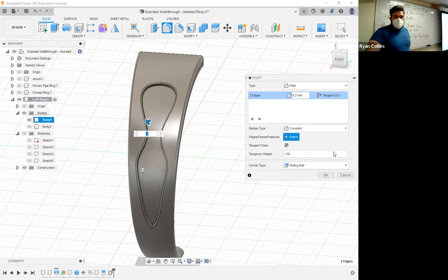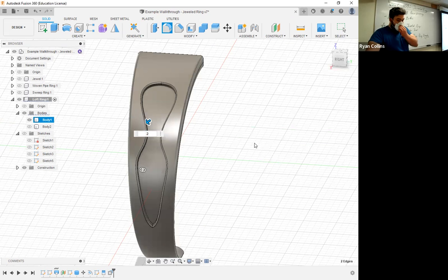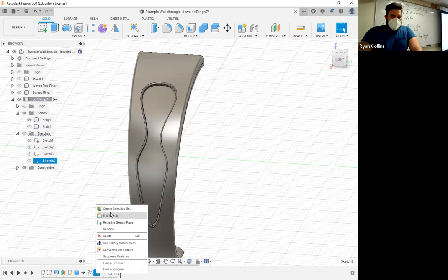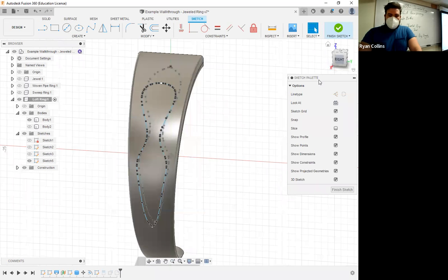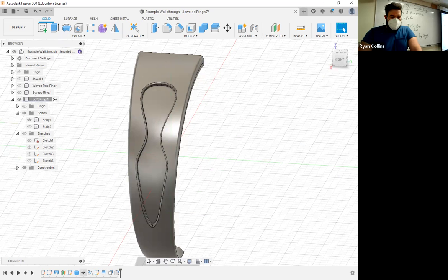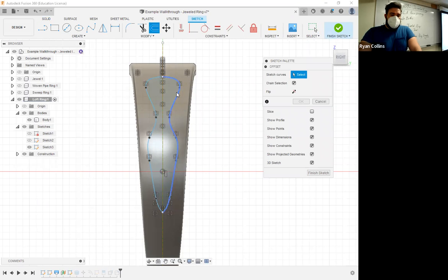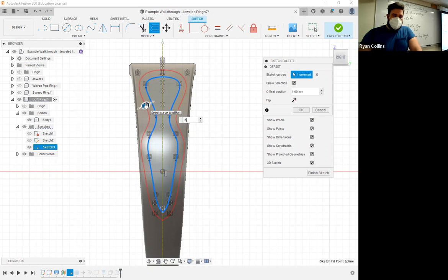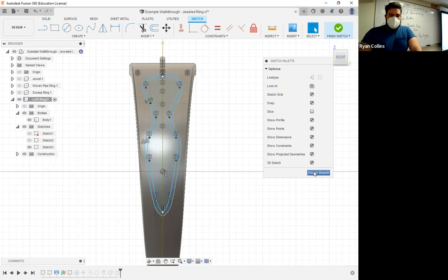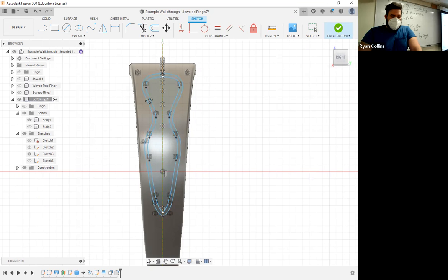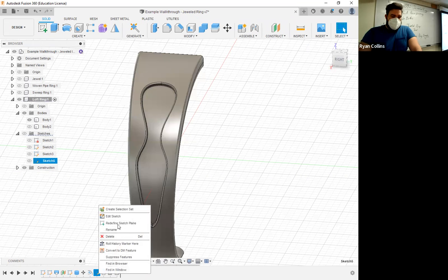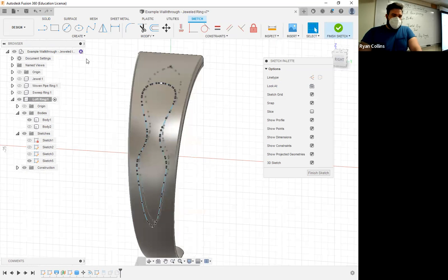The other thing you could have done is, let me see, click OK. So let me go back to, sorry, I'm trying to get underneath here. Edit sketch here. Nope, not that one. I want to use, where is my drawing? There we are. So that one, the original, I can do an offset and make two. So let's say offset of, I don't know, 0.5, slightly larger. Cool. Okay, finish sketch. Do the same. I don't know why I have a boss in here. Go back to edit sketch with that one. That was when I was projecting.